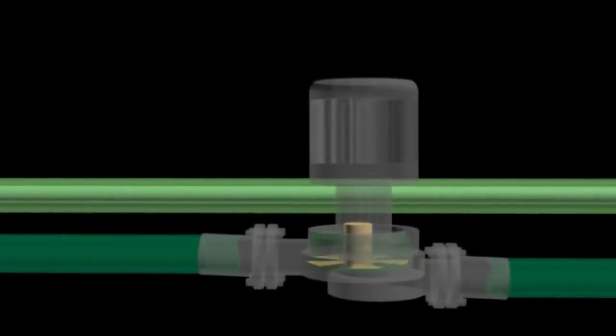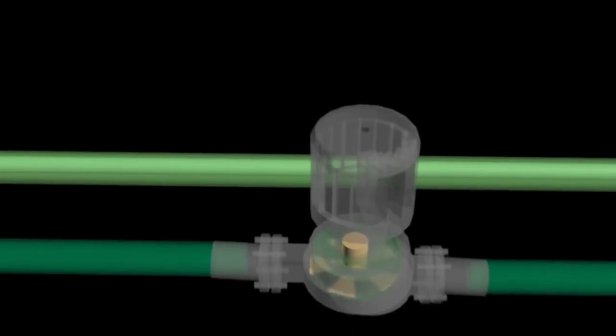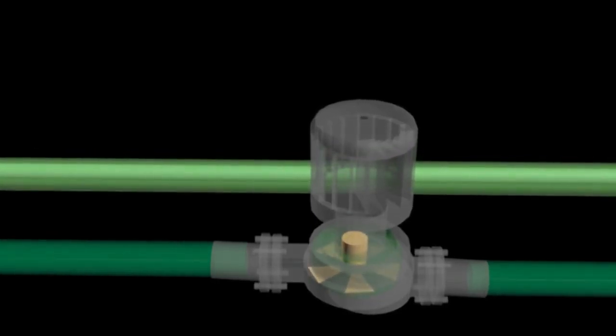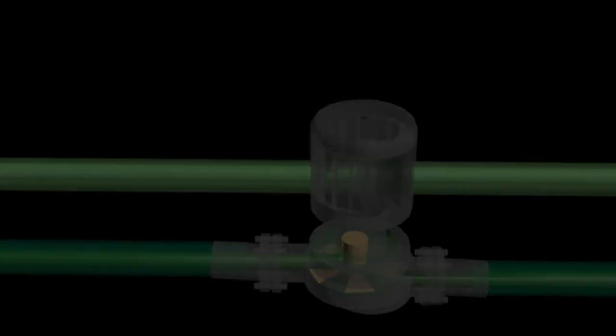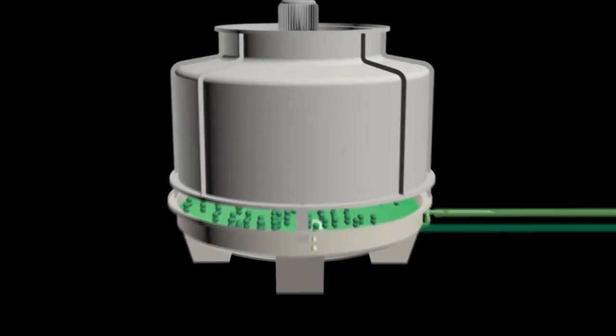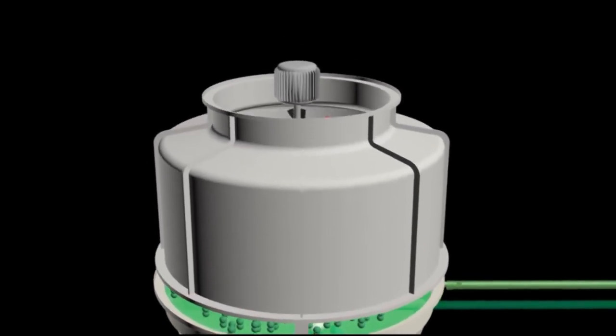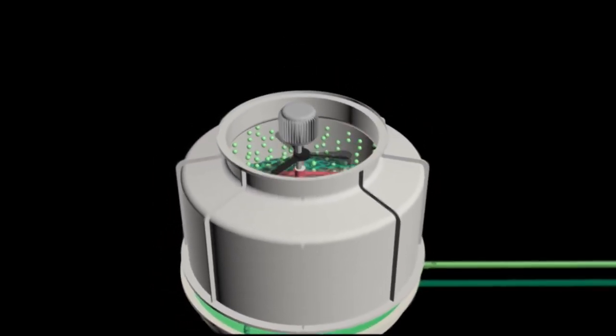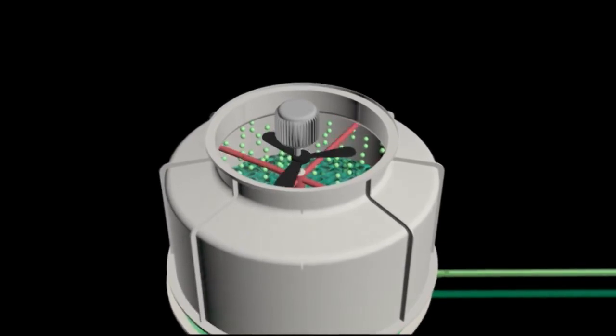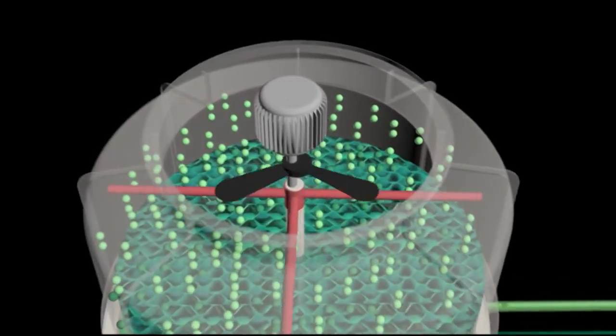From the condenser in the chiller, condenser water flows to the cooling tower with the help of a centrifugal pump. This water is called condenser water return. This condenser water will pass through the rotating sprinkler blades on the cooling tower. The rotating blades use pressure generated by the condenser water itself.